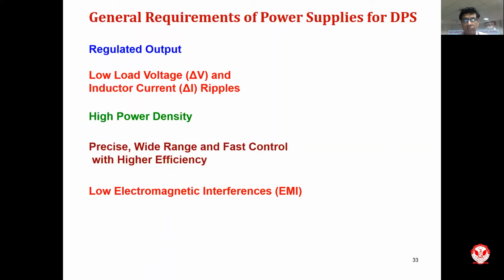One very good example that clearly depicts this picture is the Intel processors, which we are all aware of: core i7, core i5, and the 7th, 8th, 9th, 10th generation processors. If you pick up the data sheet of any of these processors, you will find that they operate at a very low voltage, somewhere around sometimes 3 volts, or sometimes even 1.5 to 2 volts. And can you just imagine what current capacity they must be requiring? If you just think.